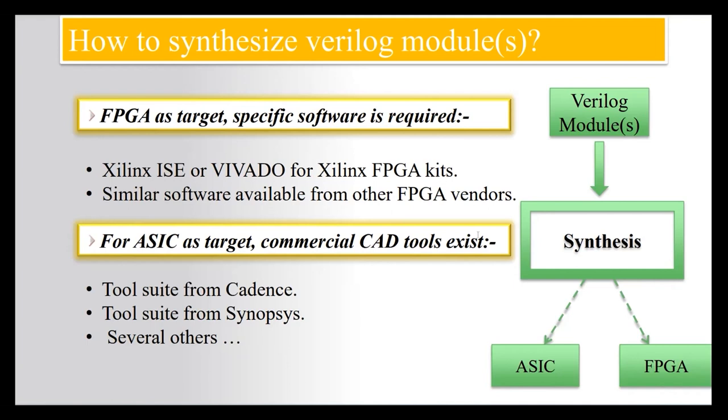Designing first the specification, taking the specification, writing the RTL design, verification, physical design, floor planning, routing, timing evaluation. All these things are there, right? So to manufacture the ASIC chips, which are permanent chips, we need to follow all these things. We call those an application specific integrated circuit, nothing but ASIC.